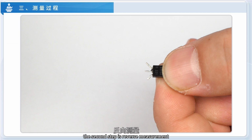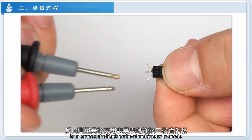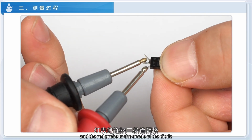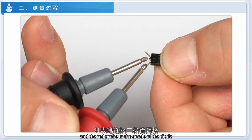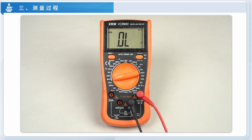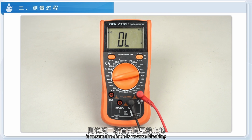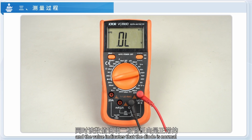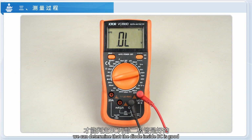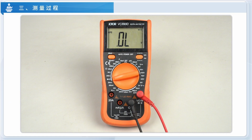The next step is reverse measurement. Reverse measurement is to connect the black probe of the multimeter to the anode and the red probe to the cathode of the diode. If the multimeter display shows OL, it means the diode is reverse blocking, and the value indicates that the diode is normal in reverse. With forward conduction and reverse cutoff, we can determine that the diode inside BC is good.